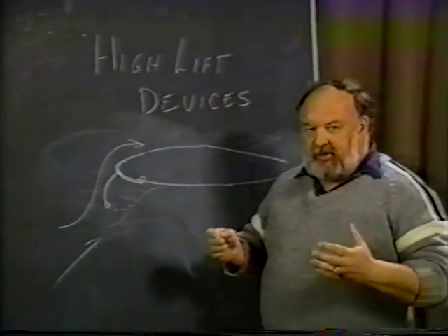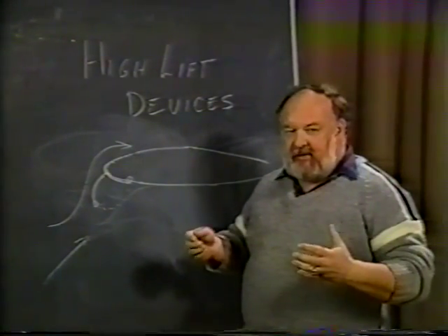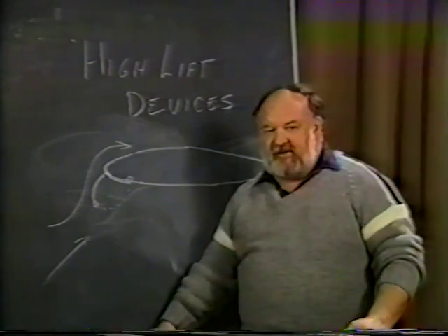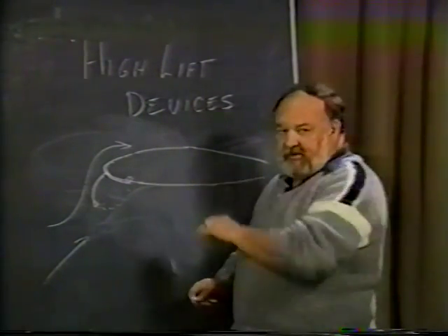You actually can feel turbulence within the airplane when the Krueger flap comes down, the leading edge flap like this, and there will be some vibration, but it's not a situation of flow separation like you have over the top of the wing.